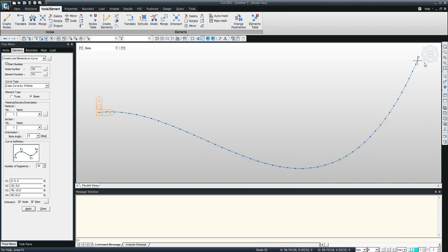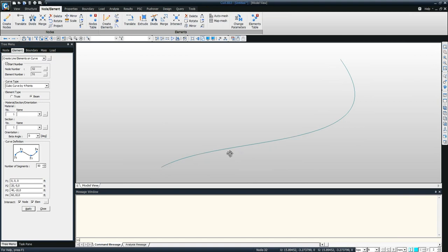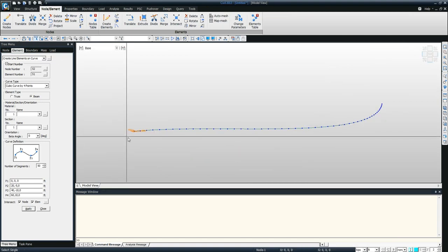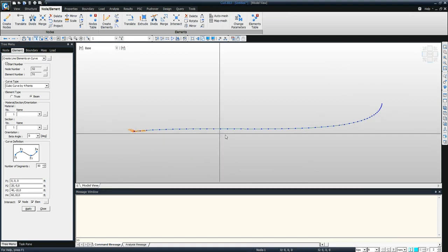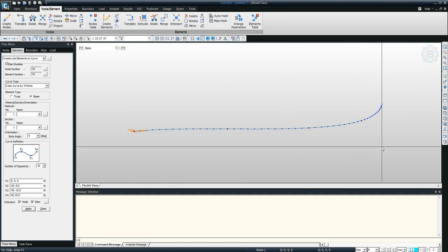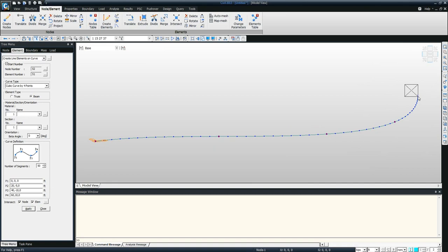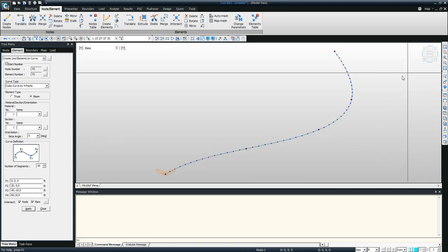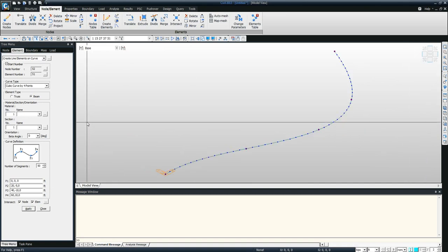This is the element that we have just created. Let's say I want to create supports at 4 locations. So I am selecting these 4 nodes here, or let's say 5 nodes. I selected all these 5 nodes, and let's say I want to create more elements in the direction of gravity. What I'll do is go to Node/Element, Extrude.